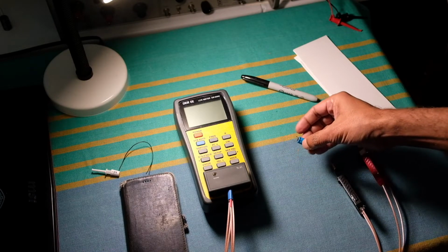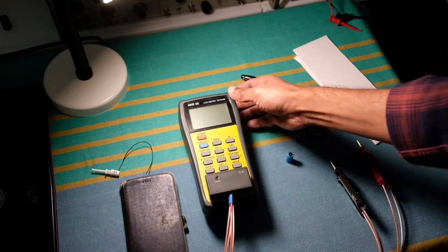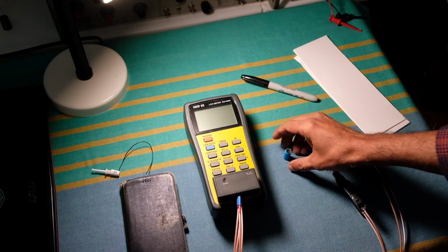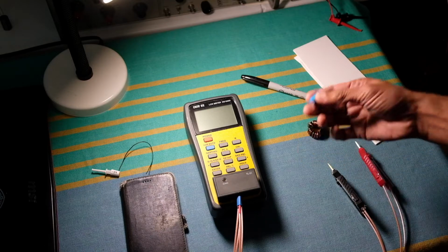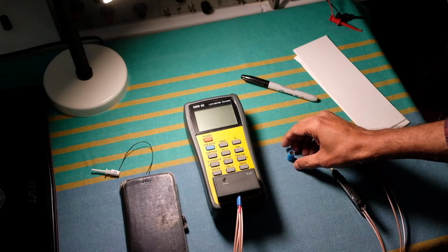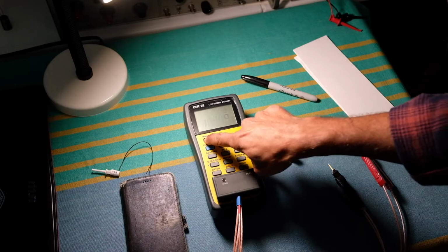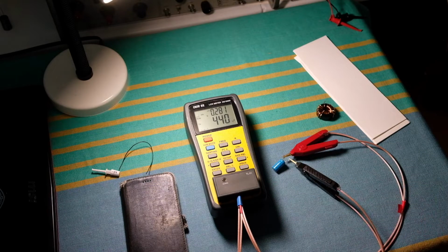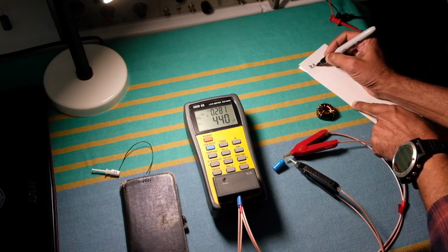So before we do that, let's do the measurement using this handheld LCR meter. This is quite accurate for certain frequency ranges, and once we do this and confirm that the effect of this inductance will actually increase the capacitance seen by the meter, it will prove the previous discussion we had on the effect of this inductance. So let's measure the capacitance first. We have a capacitance of 440 microfarad at 1 kilohertz. So we'll do the measurement at 1 kilohertz.